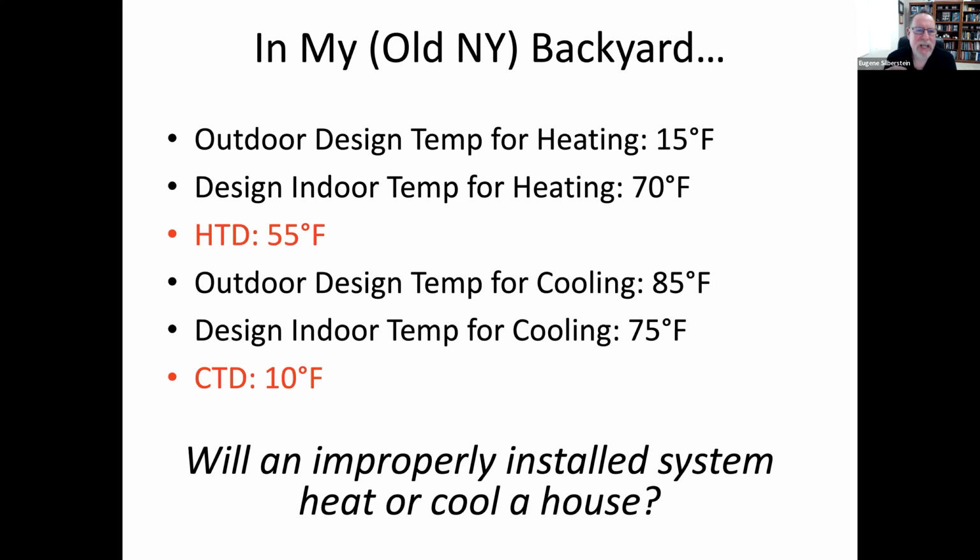Now, if we look at that same system in the heating mode, we're designing a system at an outdoor temp of 15 degrees on Long Island and an indoor temp of 70 degrees. So we're asking a system to push heat against a 55-degree delta T. So if the system is not properly sized, if it's not properly installed, if it's not properly charged, if it doesn't have proper airflow, a heat pump system that's operating in the cooling mode might be able to satisfy the cooling needs of the space by simply running a little bit longer, and the house will be cool.